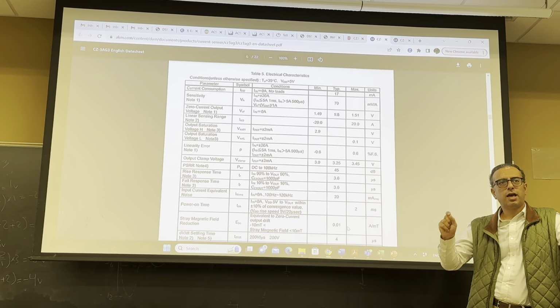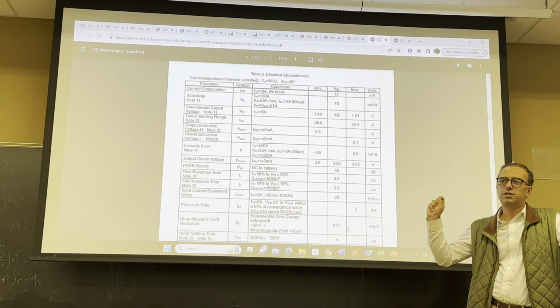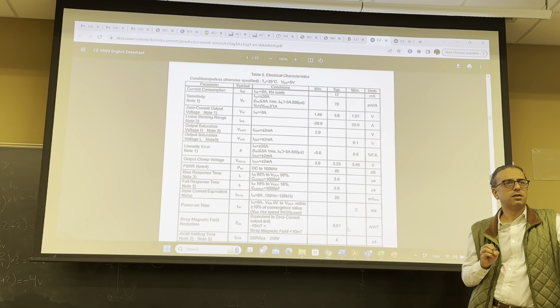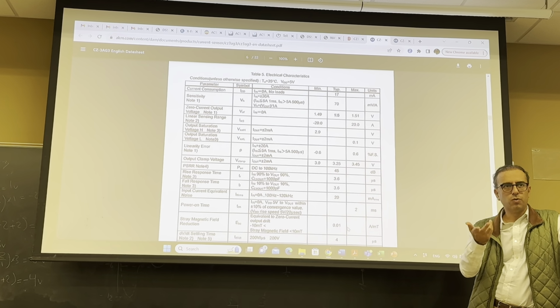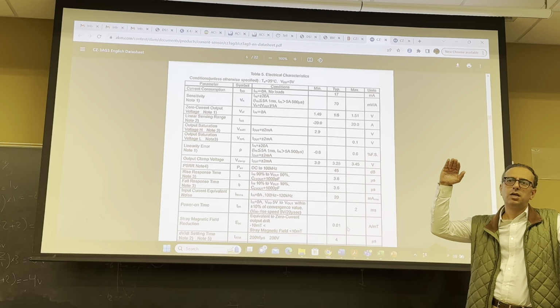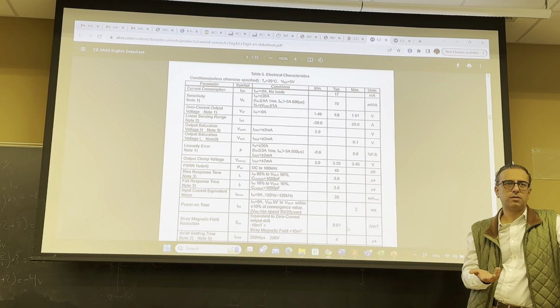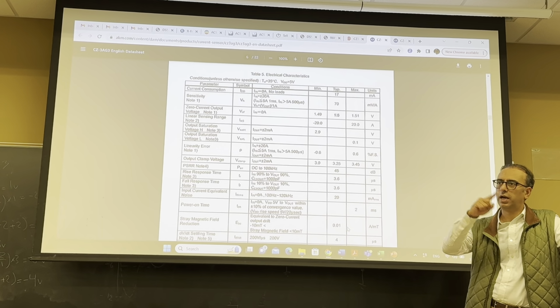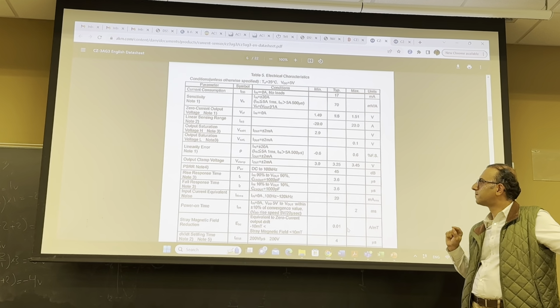If it's negative 20 amps, the output of the sensor is zero. If it's positive 20, it's positive 3 volts. So the full range is 0 to 3. Does that make sense or no?